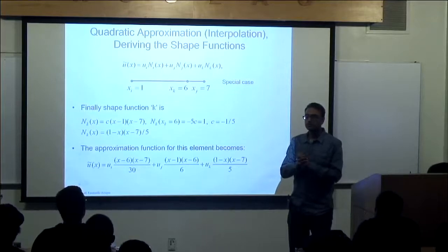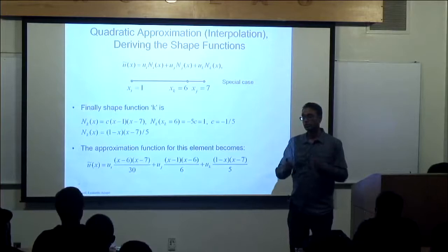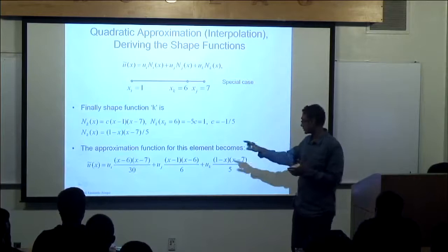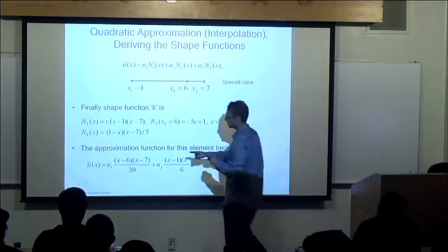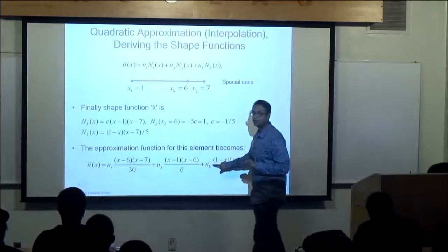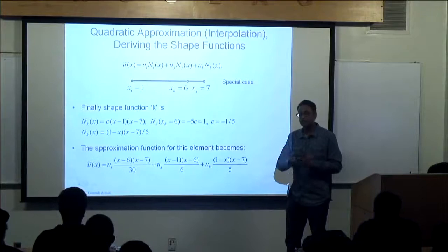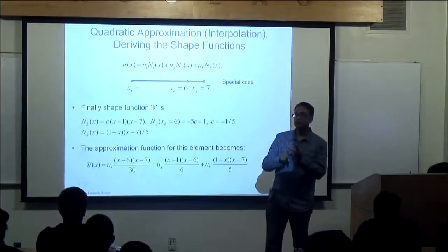So what the shape function is doing, first of all, is the basis function, which is very important because you're making the error, the residual function, orthogonal to the space of basis functions. The second thing the basis functions, which are the shape functions, are doing for you is allowing the unknown coefficients to be ones that have physical meaning. In addition to that, the basis functions actually have shapes, and they allow you to have two important properties, completeness and convergence, and we cover that.